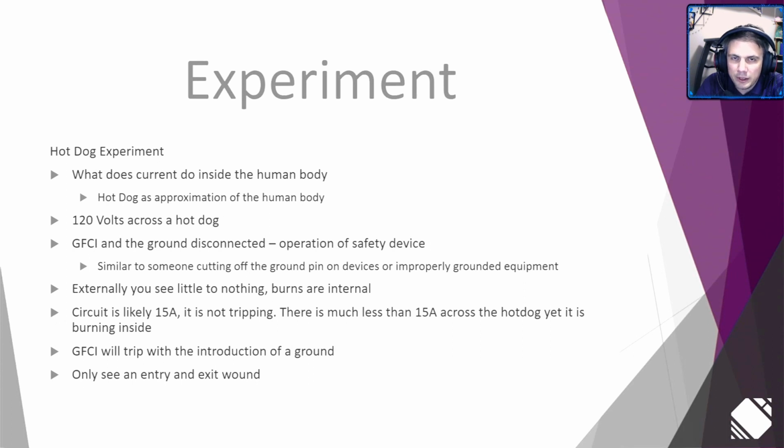Be safe, wear your PPE, make sure that as an engineer you're not actually getting anywhere close to the power. Let the electricians do their job, trust them to give you advice with your designs. A lot of times clients will have their electricians review your design before you seal it and issue it IFC, issued for construction, so that they can put themselves in the mindset of working on that piece of equipment, and they can identify additional concerns or improvements to your design to improve their safety once it's all installed. Take their advice, listen to them.